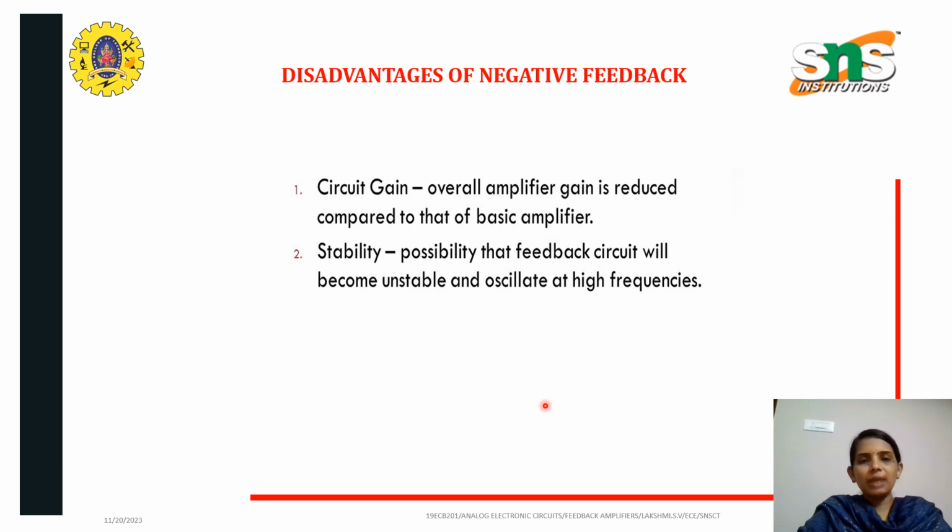Disadvantages of negative feedback are that the overall amplifier gain is reduced compared to that of the basic amplifier. And there is a possibility that the system might become unstable, as no system can be completely stable, and the amplifier might oscillate at high frequency.